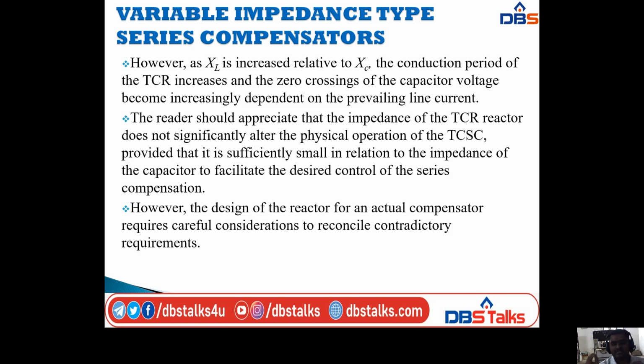the impedance of the TCR reactor does not significantly alter the physical operation of the TCSC, provided that it is sufficiently small in relation to the impedance of the capacitor to facilitate the desired control of the series compensation.